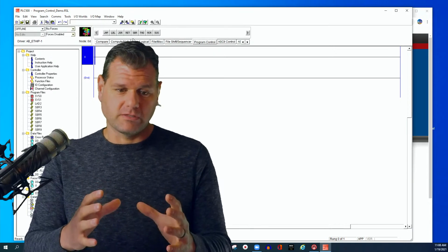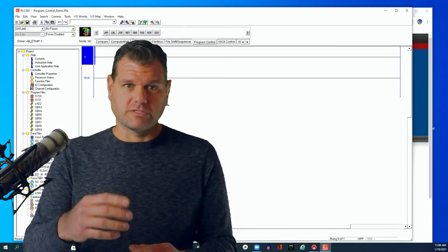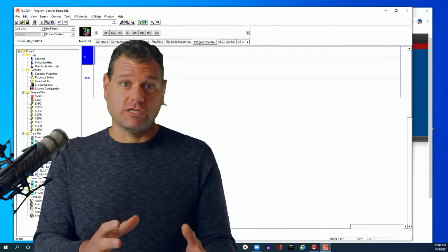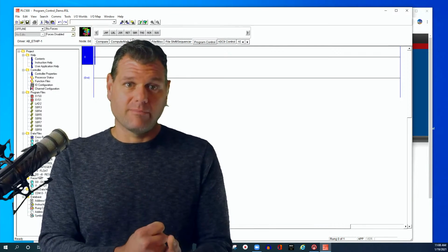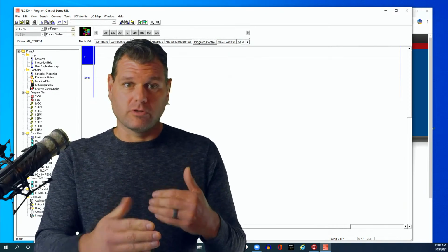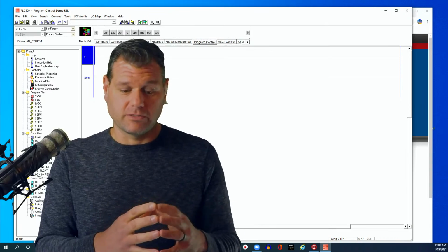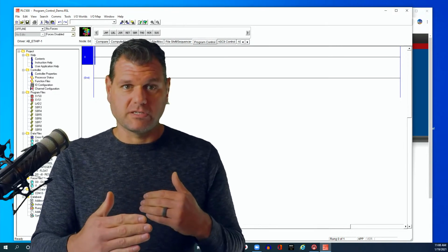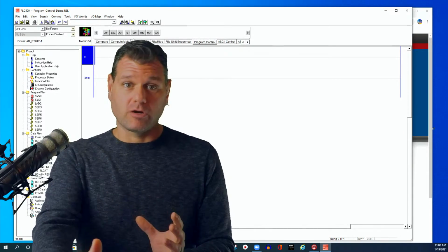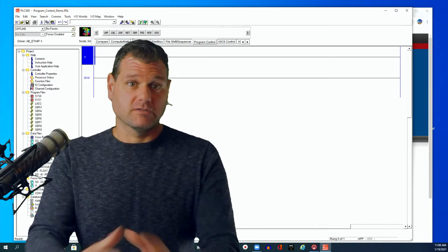So if for some reason something bad happens, let's say someone's getting their hand caught in a machine, or something's catching fire, you can hit an e-stop or some kind of stop system, and it will disable or pull apart the circuit with an electromagnetic switch, a contactor. Once that disconnects, we lose power to the entire system, or at least that part of it, and it just dies, right?